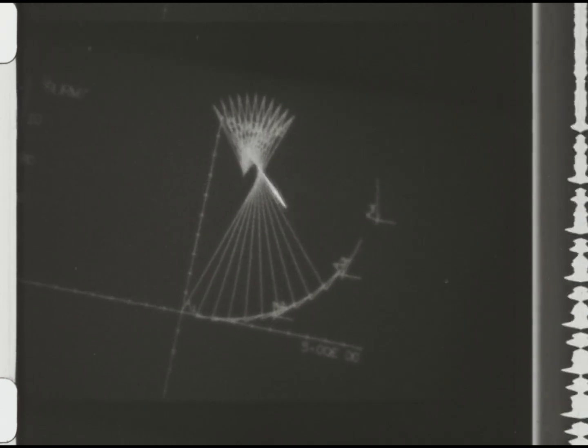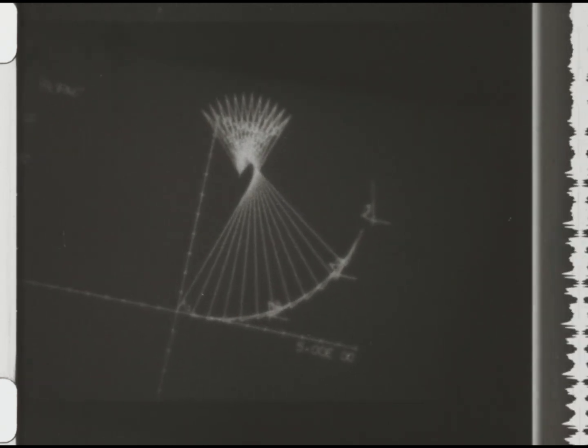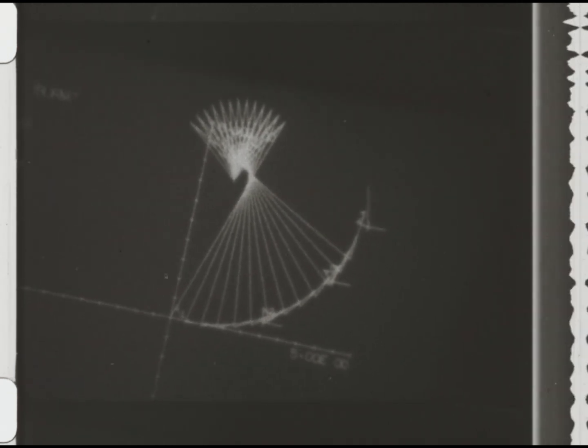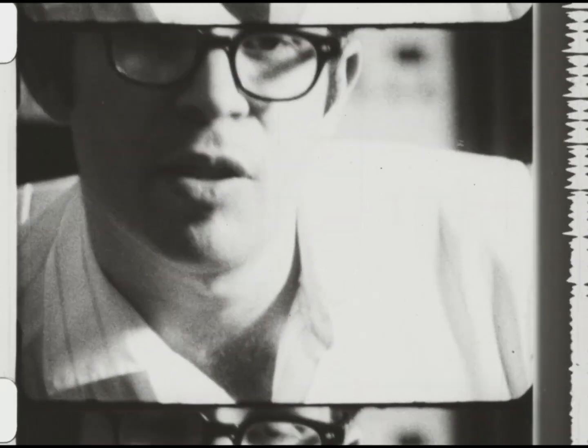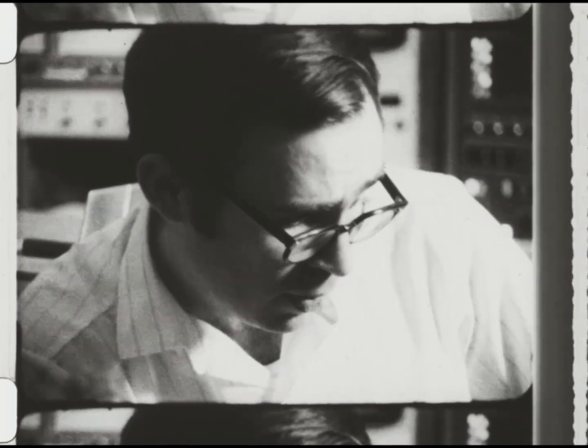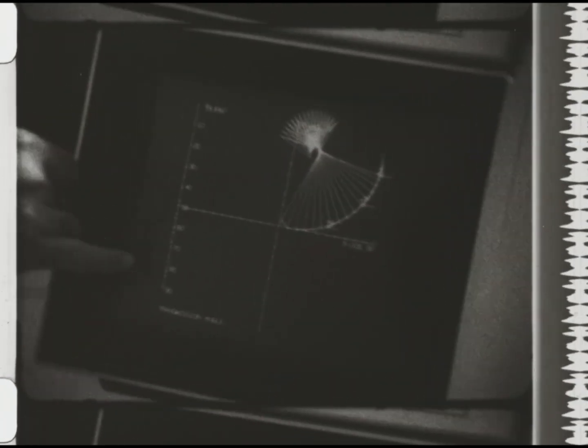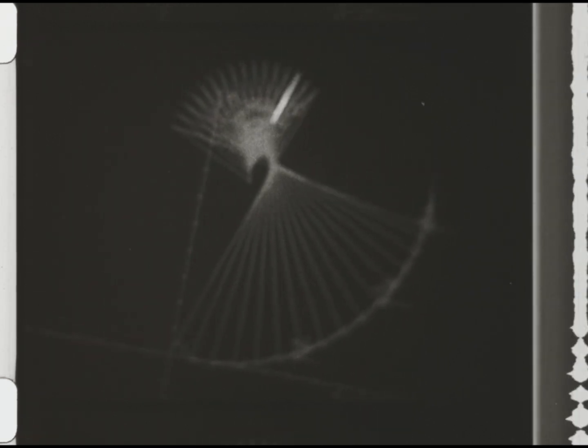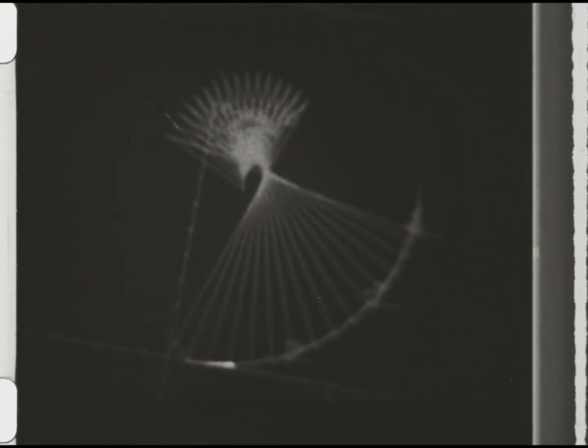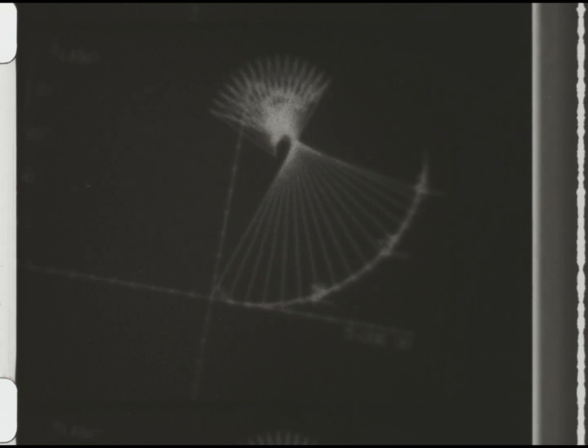This is a slider crank mechanism. It's a very compact linkage so that it would be possible to design a leg brace that would be quite compact and would not take up too much space. As a result, it's kind of crowded in there on the display and a little bit difficult to see. But you can see over here the tick marks which indicate exactly what the transmission angle for this linkage is with the particular link that is driving.